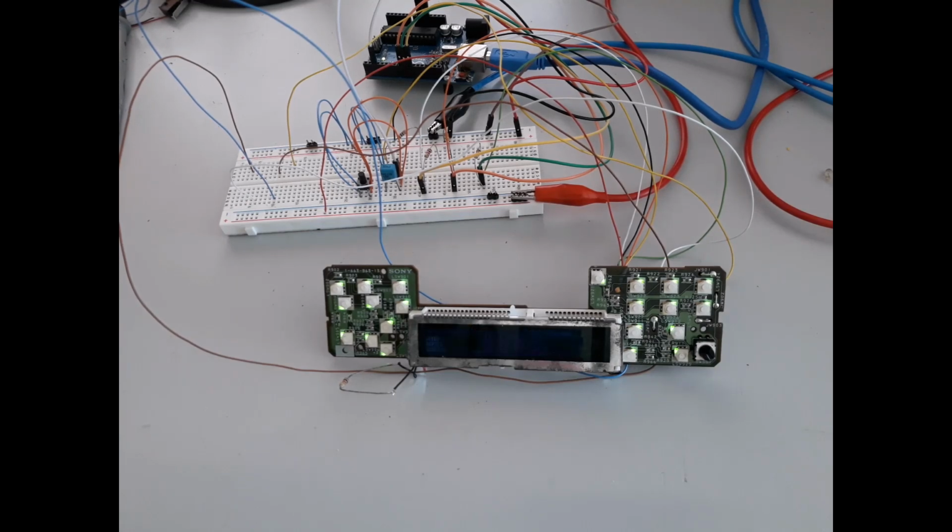This driver supports up to 4 times 36 segments and has the option that the first 8 bits can be defined as a segment or output pin. For this reason, we see the jump of the first 8 numbers used in the process of identifying the segments.